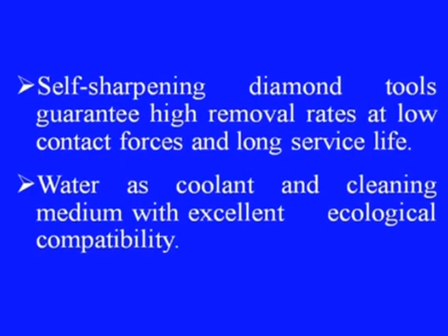Protection of workpiece and tool can be achieved because of reduced contact forces and low thermal stress. Self-sharpening diamond tools guarantee high removal rates at low contact forces and long service life. Water as coolant and cleaning medium with excellent ecological compatibility can be achieved. As we know, water is the main working fluid in this ultrasonic machining system.